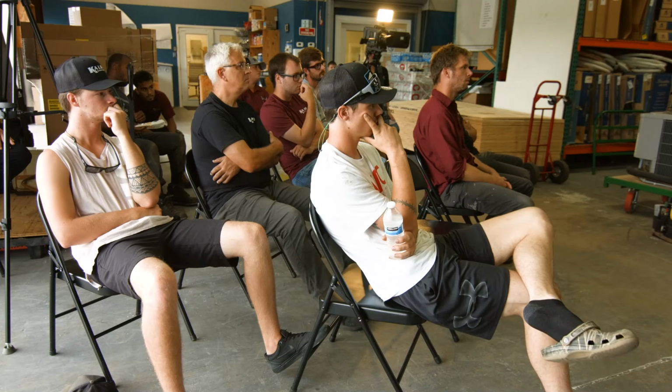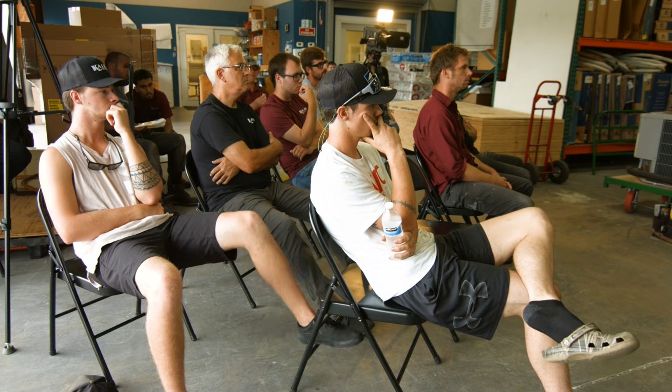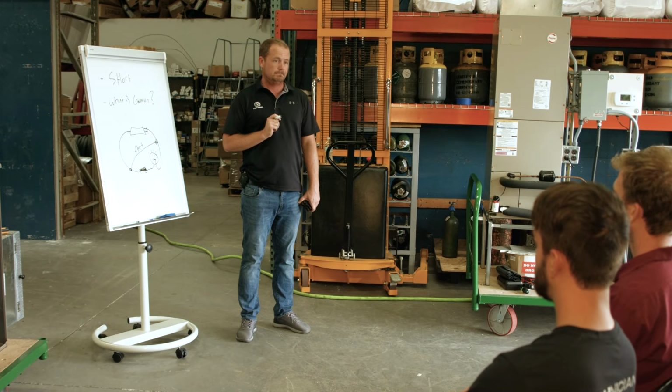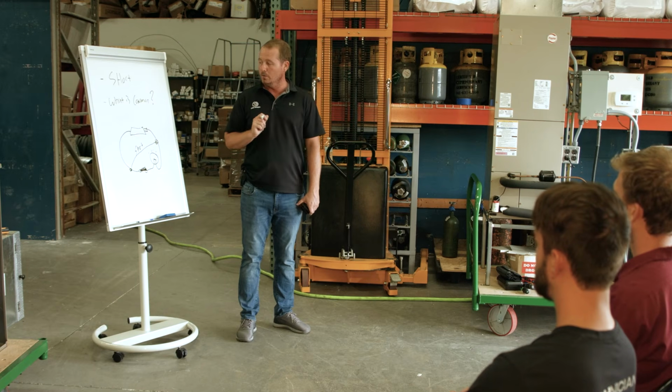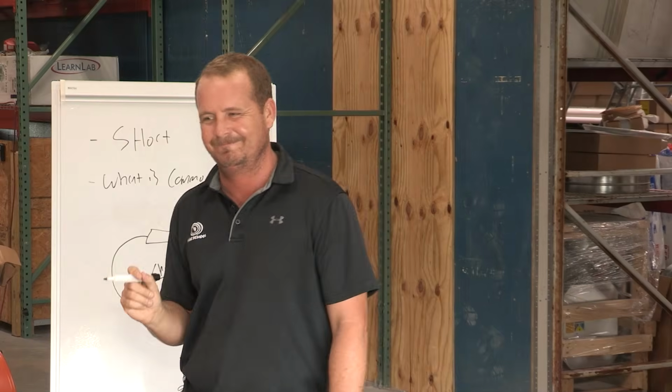So this guy right here is a short. You've got a path that's not supposed to be there. It's bypassing the resistance, and it's making the fuse blow, right? Too much current. So that's what a short is. It's very specific. Now, there's a different kind of short.